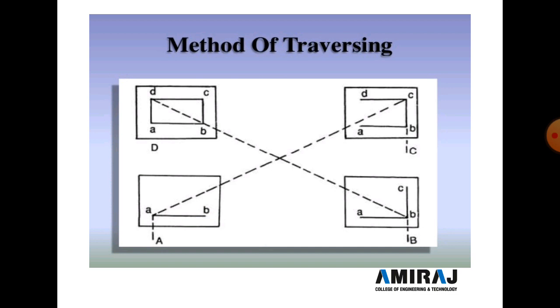all the setup is transferred to the B point, and from the B point bisect the A point ranging rod. On the B point a wooden peg is marked, and the A point and C point are marked by ranging rods. From the B point the 3 steps are also repeated: leveling, centering and bisecting or orientation.